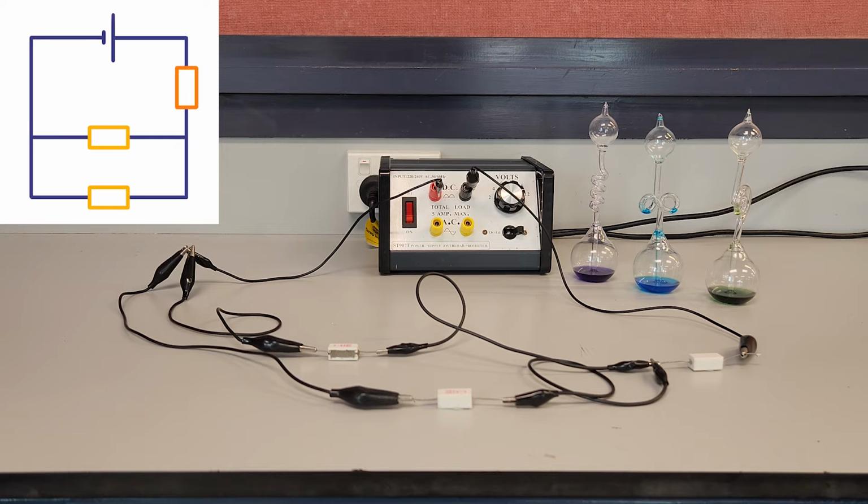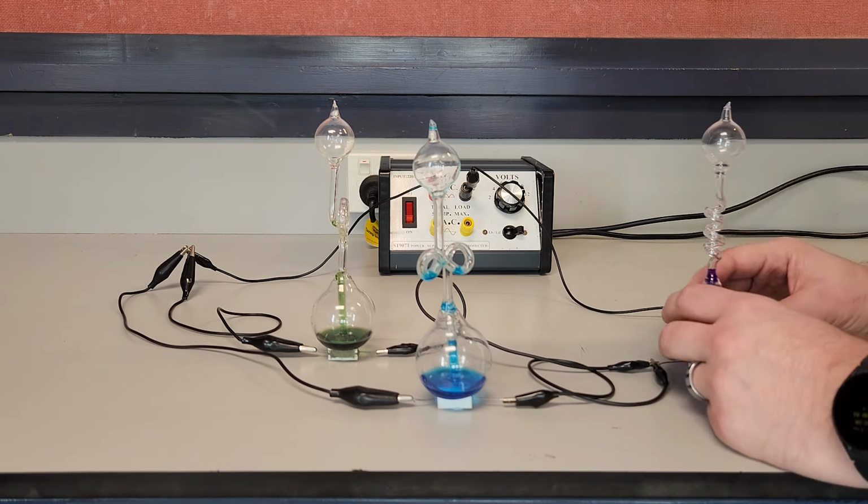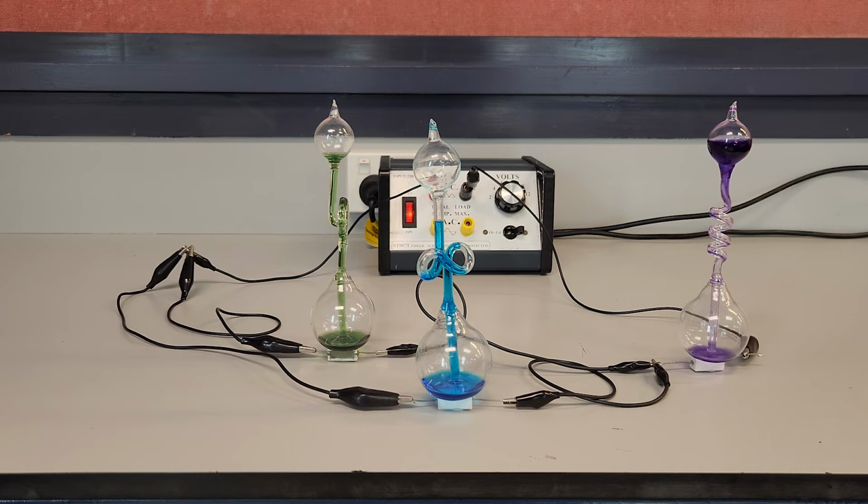I have here 3 identical resistors, 2 in parallel with another in series, and 3 hand boilers, which when heated from below force liquid from their bottom bulbs to the top. Balanced on top of the resistors, they provide a visual reference for the amount of power each resistor is consuming. We see the resistor in series consuming significantly more power than the 2 in parallel.